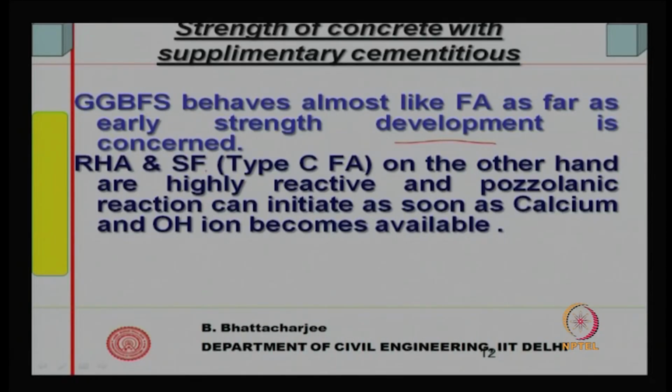But silica fume, and some types of CFA and rice husk ash, on the other hand, are highly reactive in the pozzolanic reaction, and can initiate as soon as calcium and hydroxyl ions become available. So, sufficient concentration is not really required. Besides, silica fume is very fine. If you look at silica fume, it is the other extreme. Silica fume is very fine, and fine silica fume gets into the pores of the cement system.